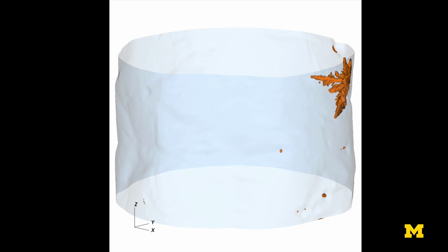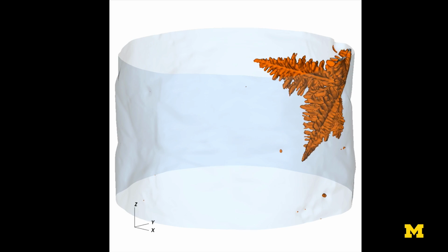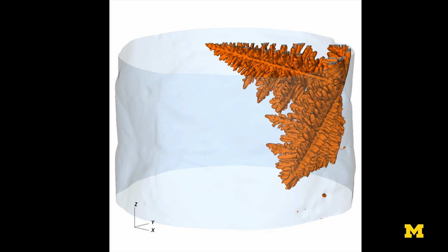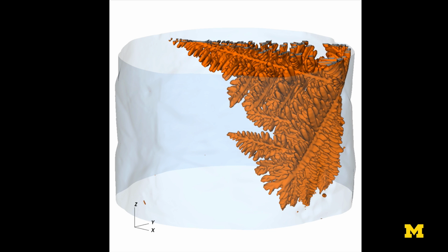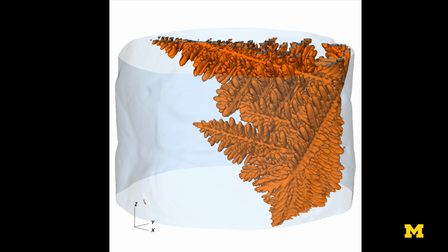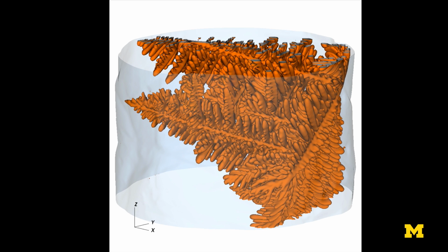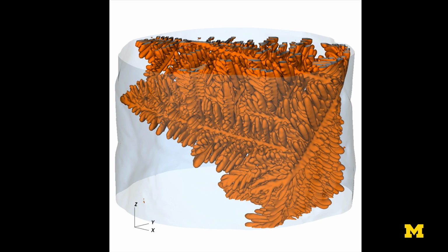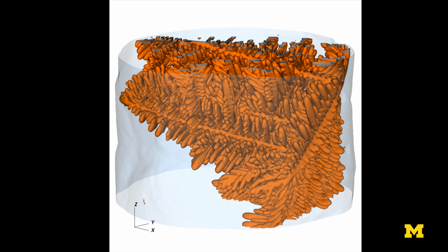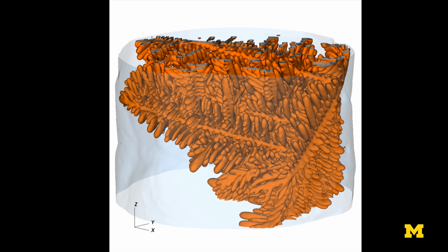So this is our 1 millimeter diameter sample. This is liquid, and that's the growth of an aluminum dendrite from the liquid. It doesn't look very much like snow, and I'll explain why in a second. We'll get there. But you can see it's a highly complicated structure. It grows from one side to the end and eventually crashes into this end of the sample when the supercooling is expended or the supersaturation is expended and begins to slow down.